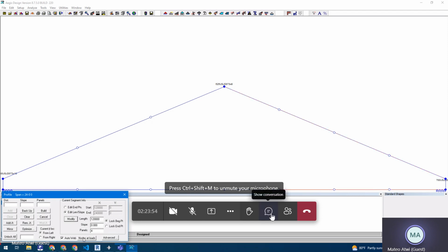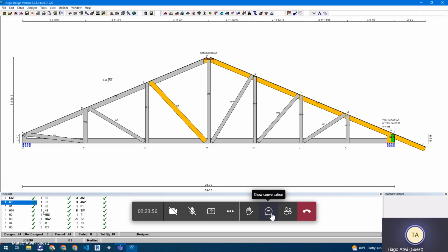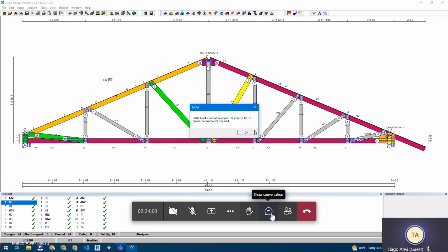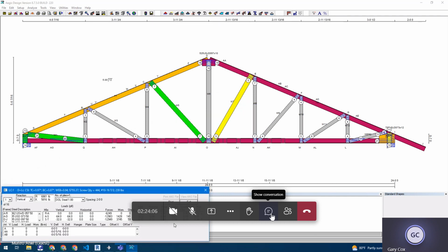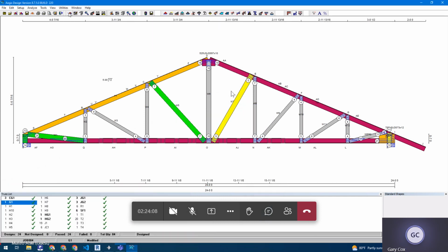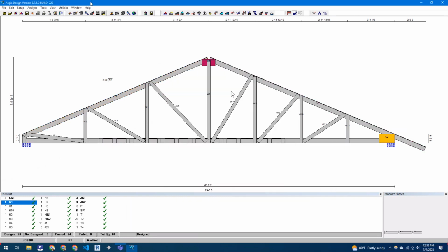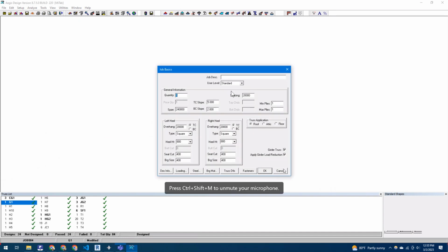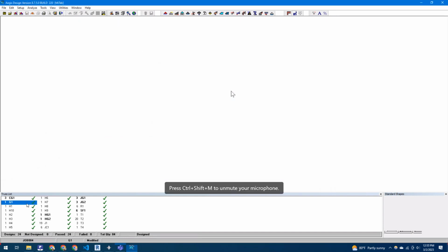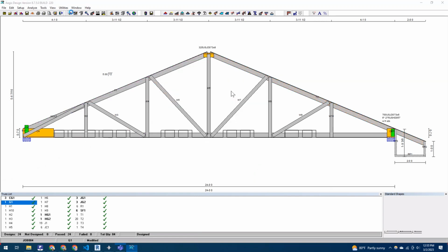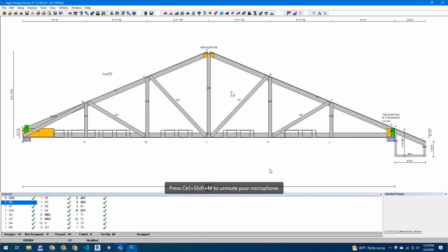Was Tiago trying to check something? Yeah, I just had a question about splicing two trusses together, if it's really long. Well, really long depends on how long you can ship. Mostly you just have it on the table and put it together, but don't screw it together at certain points. And then when they get it in the field, you screw it together where it needs to go. The only problem with that is trying to keep it square in the field.